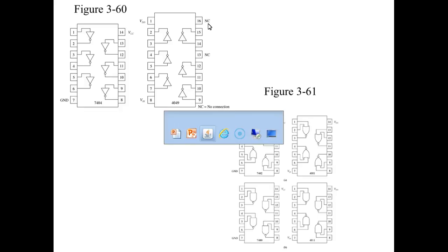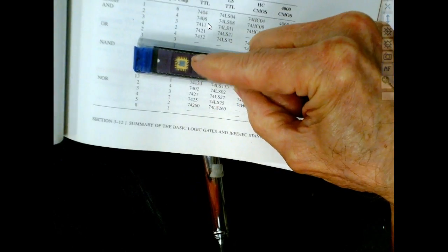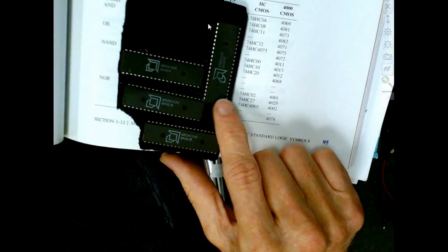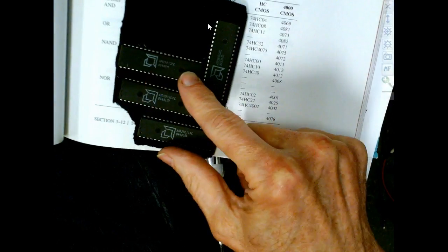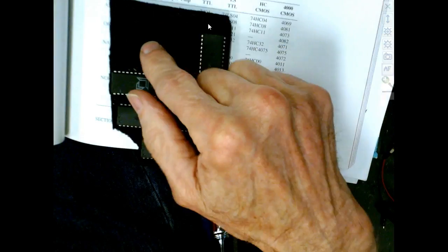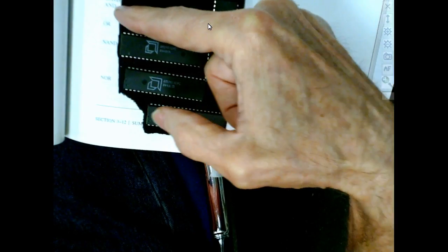Well, when they went to the 24 pin, they changed the width. Now see that? So they went to a wider chip. This went all the way up to, this is a 40-pin dip right here. I can pass these around and show you. Don't take this. These are made out of MOS, and MOS is susceptible to static discharge. So this is anti-static foam that would keep these guys in. Not regular foam. This is anti-static foam.